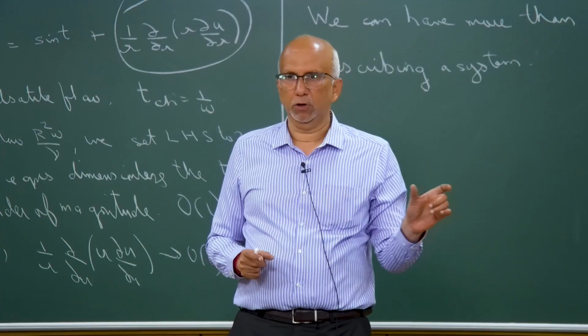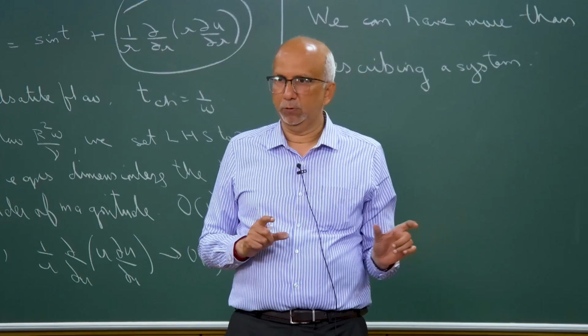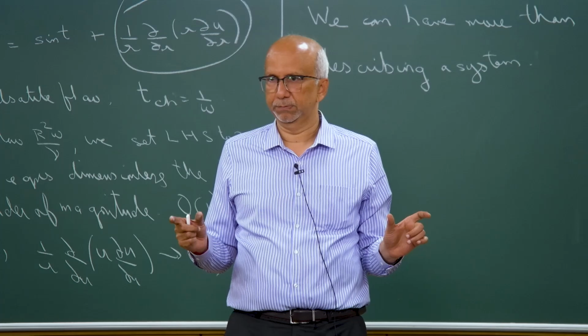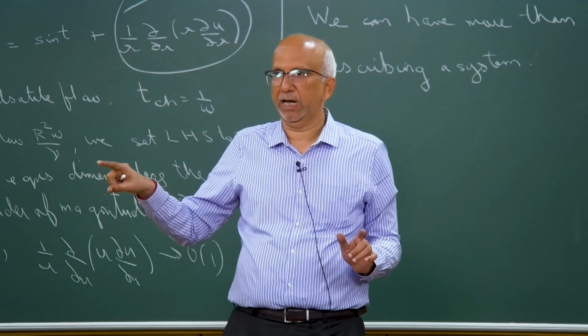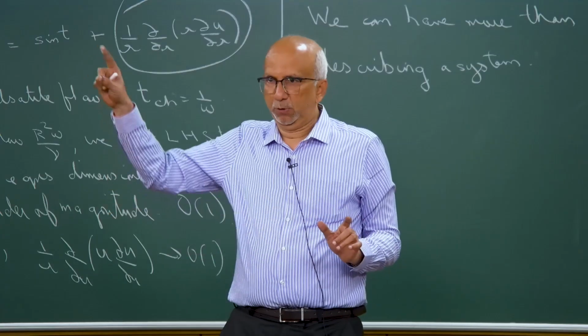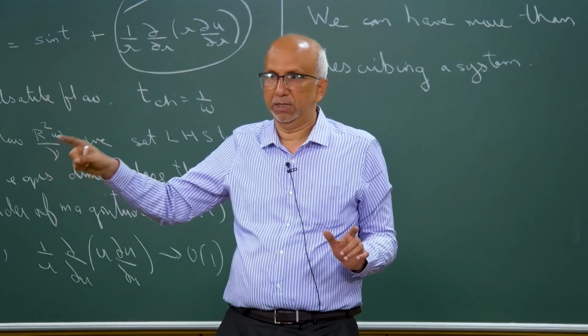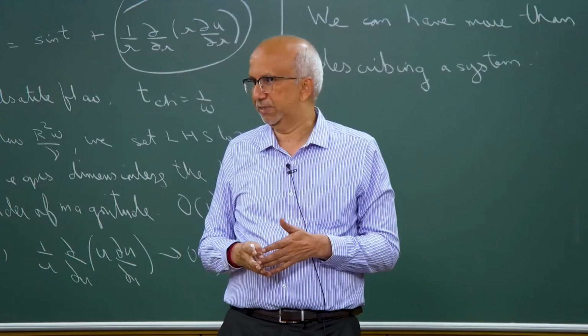So when you analyze changing the Strouhal number, experimentally you will change it by changing the frequency. But it should not affect other numbers, because when plotting a graph for the Strouhal number, you are assuming your Reynolds number is constant, or that something else is constant. If that changes because of changing frequency, then that graph does not make any sense.